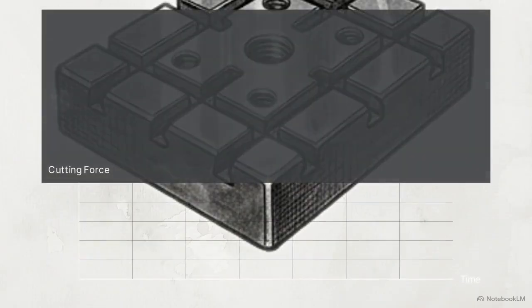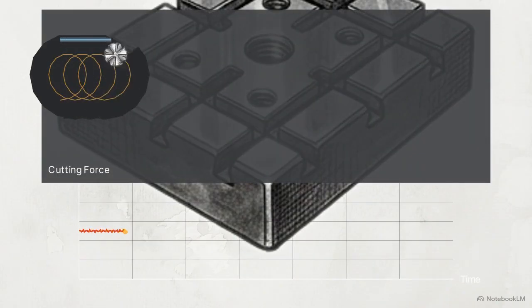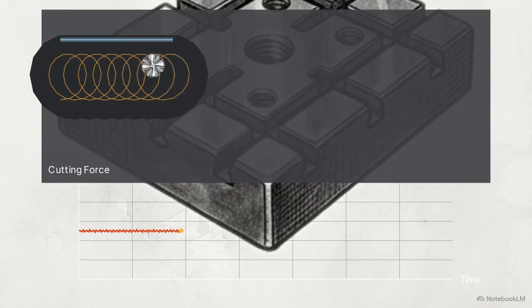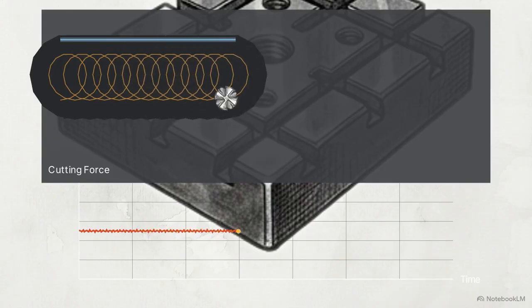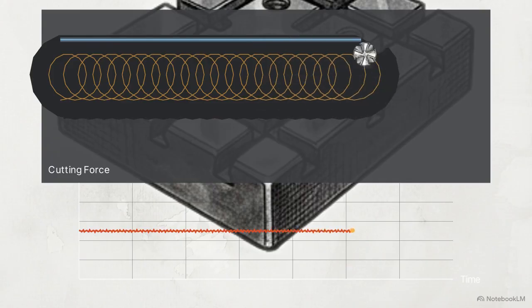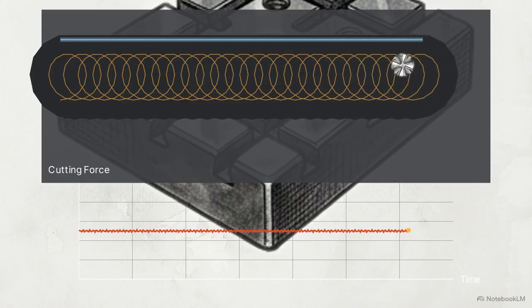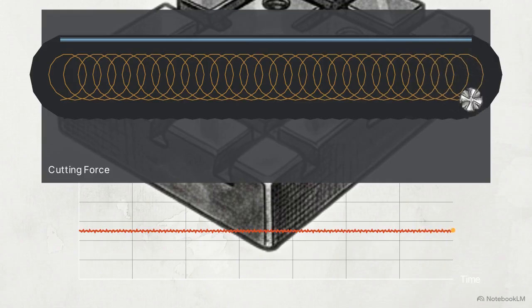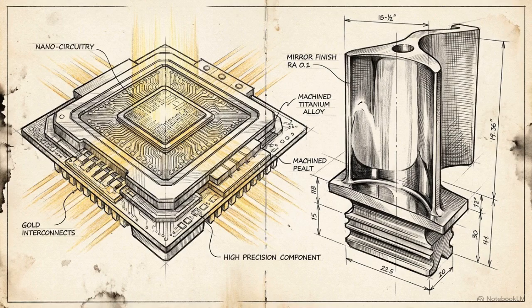In this diagram, the tool moves in a looping trochoidal path. The force gauge remains perfectly steady because the engagement angle is strictly constant. As the tool completes the loop, these steady forces eliminate deflection, leaving behind a perfectly smooth wall without jagged burrs. Software optimization extends hardware limits, guaranteeing surface consistency without extreme cooling or frequent tool changes.